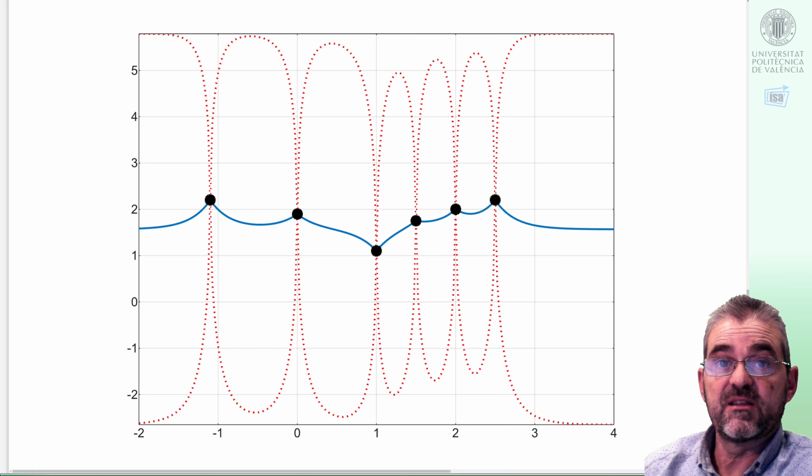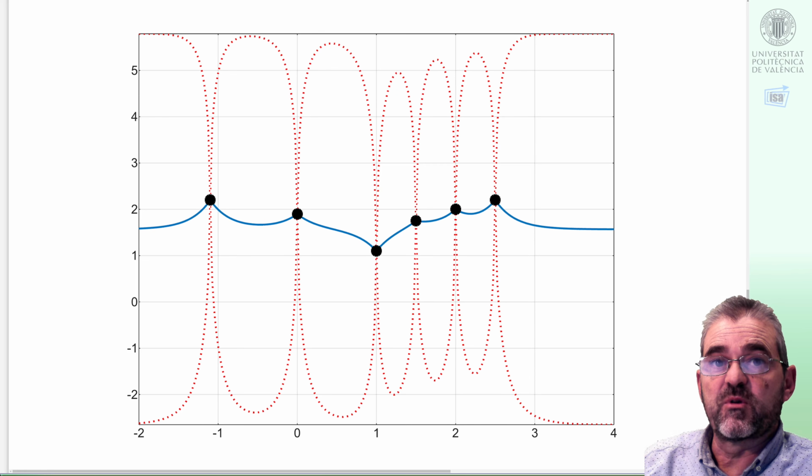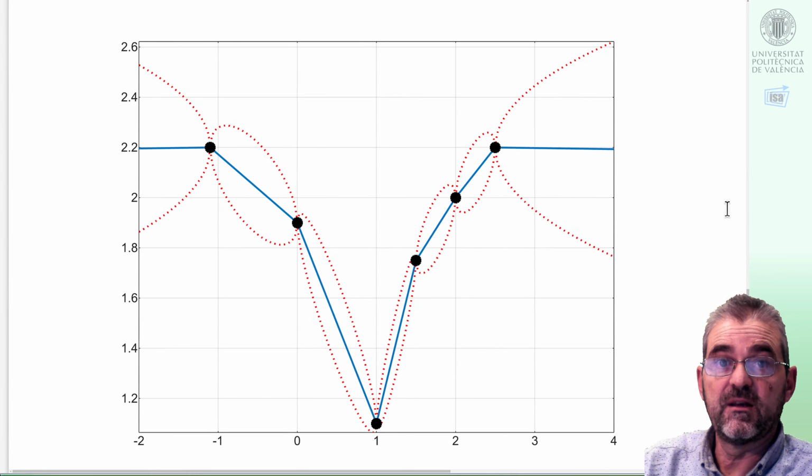We have seen that the expected value, the blue line, of the interpolation and extrapolation are pieces of exponentials around an estimated mean value whose uncertainty we included in the kernel, and if the time constant distance parameter was very long, the spectral factor was approaching an integrator, and then the result was linear interpolation between the samples.